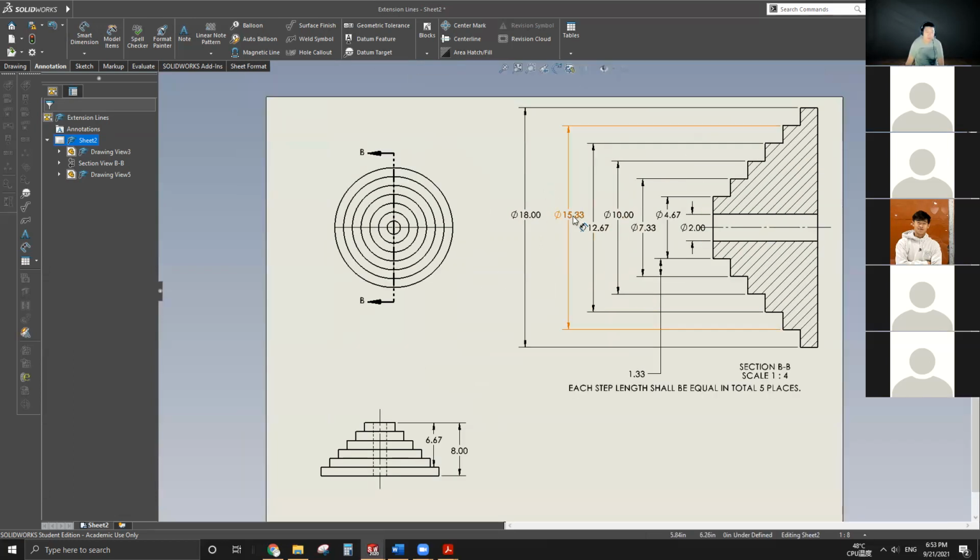So if you're removing all the dimensions in between, you're losing the ability to control those diameters for those round pancakes at the drawing level. You can only know them after the part has been made, by measuring them to see if they qualify or not. All right. I hope that answered your question.